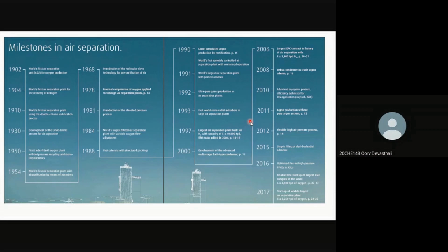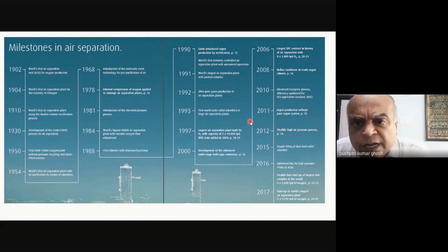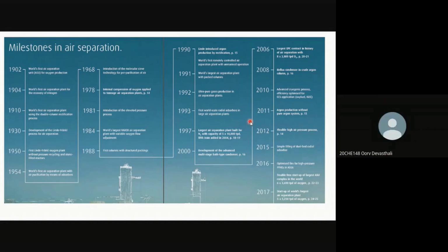Yeah. In the Solvay process, in the carbonation tower, we were using mushroom structures, right? Yes. So is that also a part of structured packings? Absolutely. Those are all types of packing. The only thing is that over here you'll probably have a much more dense packing. You understood? Yes, sir. The packing will be far more dense because of the kind of surface area that you require here. The two problems are almost an order of magnitude different in complexity, because you're talking about such small differences in boiling point. Okay? Yes, sir. Thank you, sir.